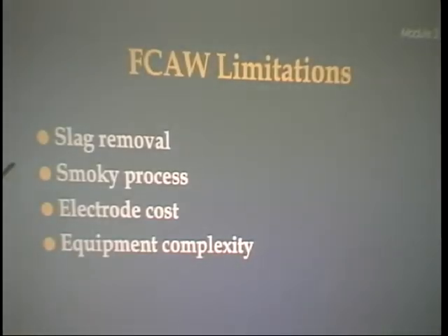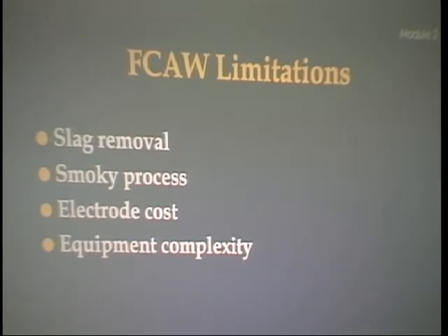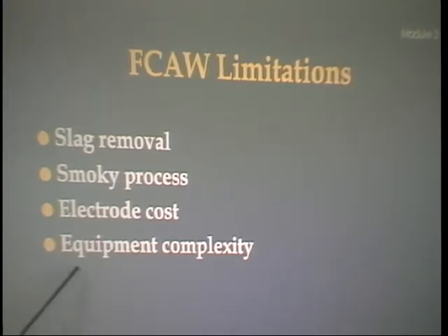Limitations. You've got to take the slag off. Remember, the arc characteristics are an awful lot like stick rod, so it's going to produce slag. You've got to clean it all off of there. You've got to make sure that you're not trapping any of it, so you're going to buff it off, brush it off, get it all out of there. Very smoky. Smokiest of all the processes I've ever been around. The electrode's a bit expensive, and the equipment is somewhat complex. So those are the limitations.